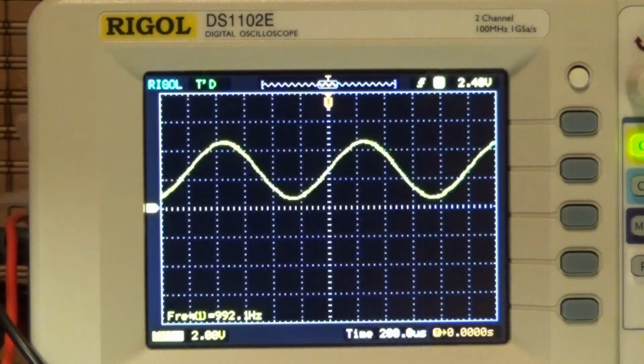In my previous video, I annotated on the video because I forgot to mention what values I'd chosen, but the value of the resistor was 12K and the capacitor was 10 nanofarads. When you do the math, you get about 1200 hertz as the cutoff frequency. I would probably have to reduce the value of the capacitor or increase the value of the resistor. Is that going to work? No. But I would reduce the value of the capacitor to get the frequency to go out a bit further.